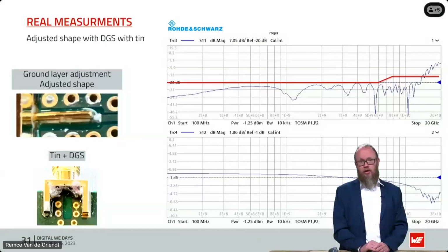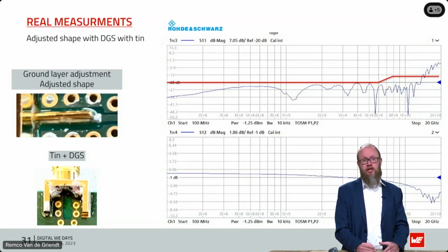Yeah, regarding signal integrity, what I already told, if you are using, for instance, a Rogers material, you already get differences in how the epsilon is changing. For instance, I already showed it's 4.5 for FR4 material, up to 3.5 for Rogers, out of my head. That changes your permittivity, so that also changes how the losses will be, especially absorption losses, so you get better signal integrity.